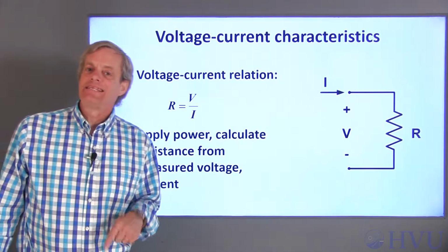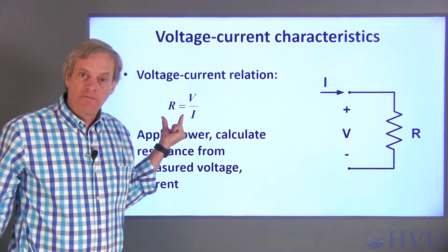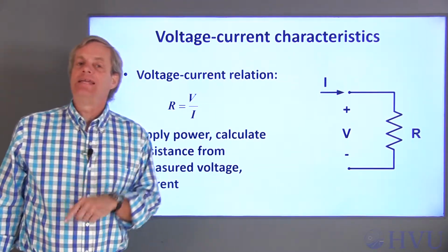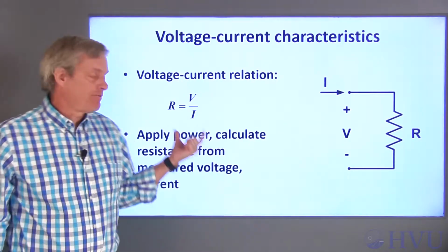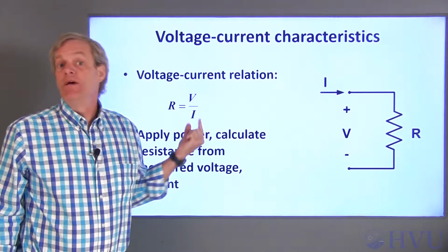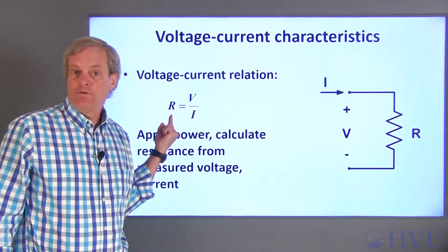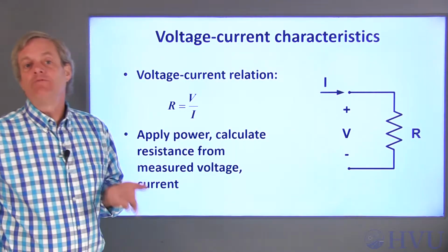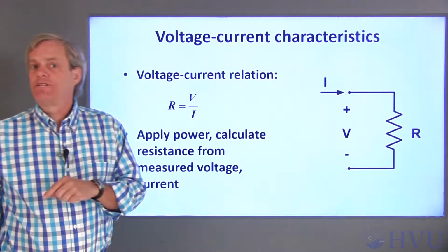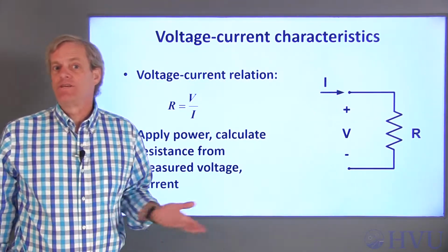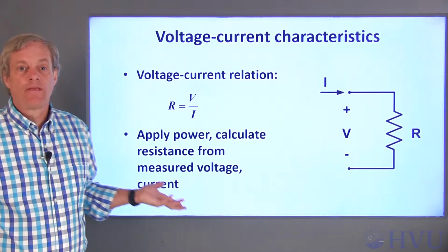When we applied a single value of voltage and measured the corresponding current, we got an estimate for resistance. However, any experimental data is prone to errors, so it's probably better to apply several different voltage levels to the resistor, measure their corresponding currents, and then calculate the resistance for each voltage-current combination. Then we can, for example, identify bad data points and disregard them, or average the calculated resistances and feel secure that a little error in any one measurement isn't completely skewing our results.